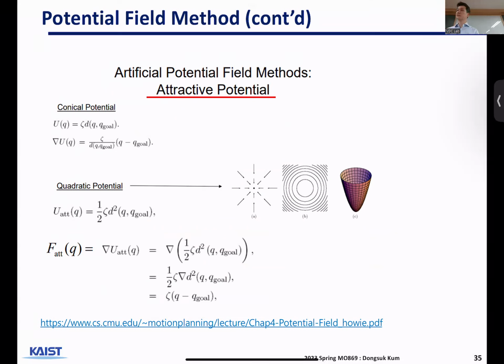Designing the potential field. That's the engineer's job, and that's the only thing you need to do. Everything else, the computing gradient, following, executing the motion is almost all deterministic. Everything is done automatically. So it's all about designing potential field. Okay.